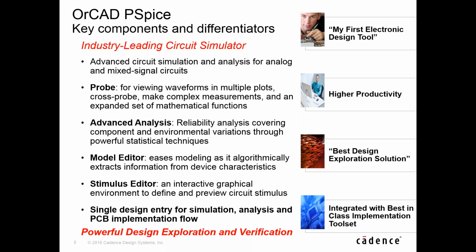Similarly, we also have a stimulus editor. It's an interactive graphical environment where users can create pulses, or they can bring in hardware waveforms, and very easily create a stimulus for your design. So basically what PSpice does is provide a single design entry for simulation, analysis, as well as the PCB implementation flow.